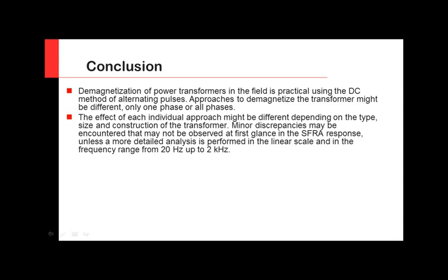This excitation voltage that is being applied, this current that is being created on the coil, right, is creating this magnetic field, and everything is moving, and your magnetic domains are going from one direction to the other direction. And now you saturated the core of this transformer with DC, and you put it on one side. In order to get those domains in a different direction, or to get back into the original position where they were at, it may take more than just all this process here. It might be a little bit difficult to do that.